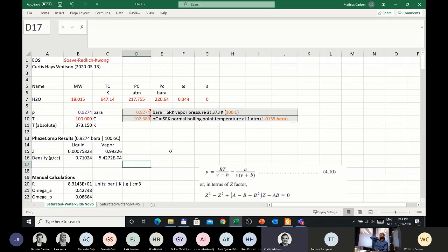The cubic equation, even though it's getting the water density exactly right, let's say 1 gram per cc at 1 atmosphere and 60 Fahrenheit, the compressibility it'll calculate won't be 3 times 10 to the minus 6. It'll be around 1.3, I think, times 10 to the minus 6, which is more than a factor of 2 too low.